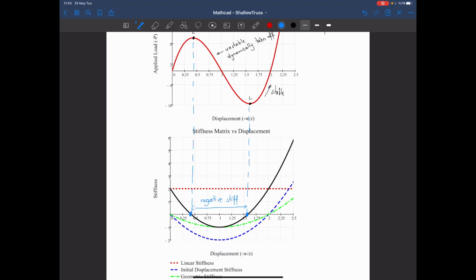So that's why the equilibrium is satisfied with a dynamic equilibrium. There's no static equilibrium because we have negative stiffness on the system, so it moves very fast, it buckles actually, and between these 2 points it moves, but as we reach the second limit point, you can see we have a positive stiffness. We see some resistance in the system, and as it moves further, we get positive stiffness and we see the resistance.